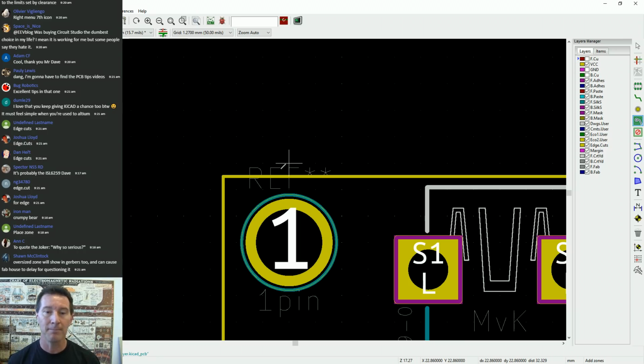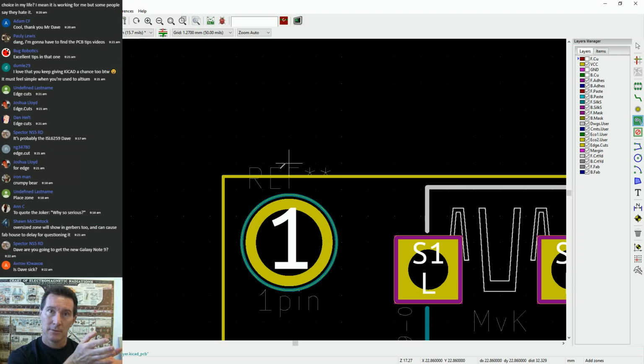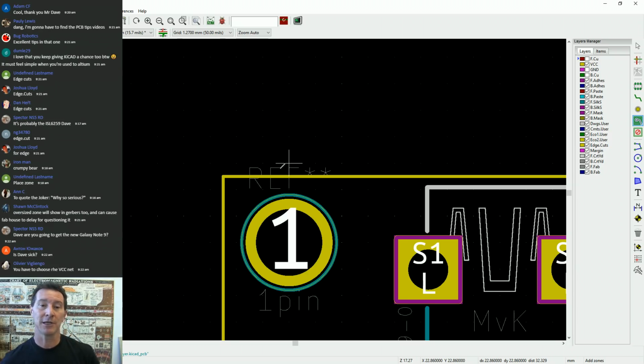And when they chop your board up, especially if it's a multi-layer board like we're designing here, a 4-layer board, that means we've got the top copper, the bottom copper, and ground and VCC in here. So what we're doing at the moment is creating these two inner layers, ground and VCC, and they're just one big solid copper plane in this particular case. Doesn't have to be. KiCAD does not have planes as such. They're just layers with polygon fills or zones.